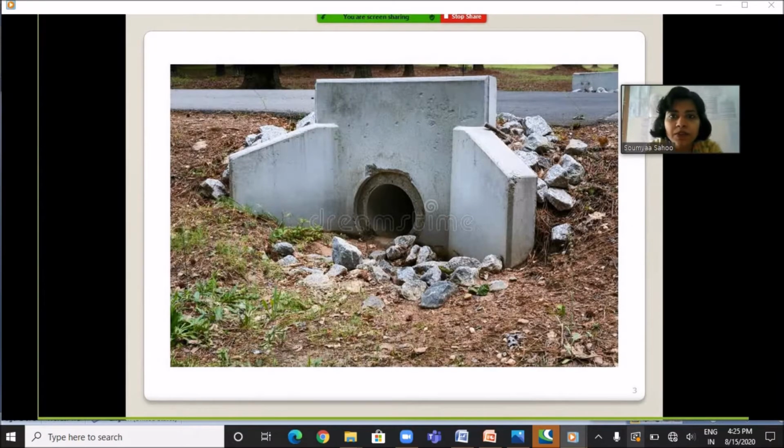Students, pipe culverts are generally provided when the discharge of the nala or the stream is very small, and in no case is it advisable that the diameter of the pipe should be less than 30 cm. If the diameter of the pipe is less than 30 cm, then the pipe is likely to get choked, and it is usually preferred to provide a splayed wing wall for the ease of approach of water.